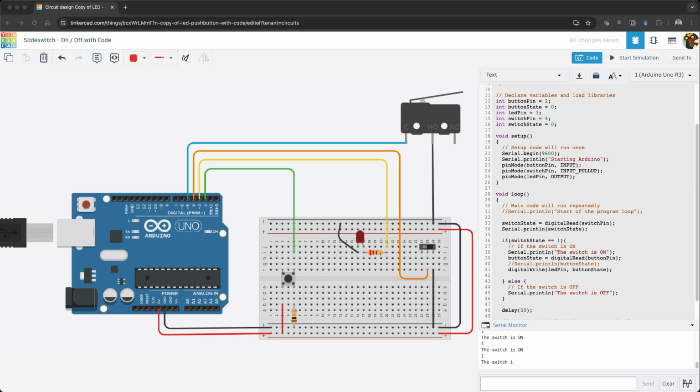In your kit, you have another SPDT switch that looks a little different, the micro switch with an extended lever. It works the same way. You will notice a common terminal, labeled COM, and 2 terminals, one labeled NO for normally open, and one labeled NC for normally closed. Note that we can use the code from this tutorial to read the value of the SPDT lever switches too. Connect a wire from COM to an Arduino pin and use INPUT_PULLUP when setting the pin mode. Connect the normally open to ground.